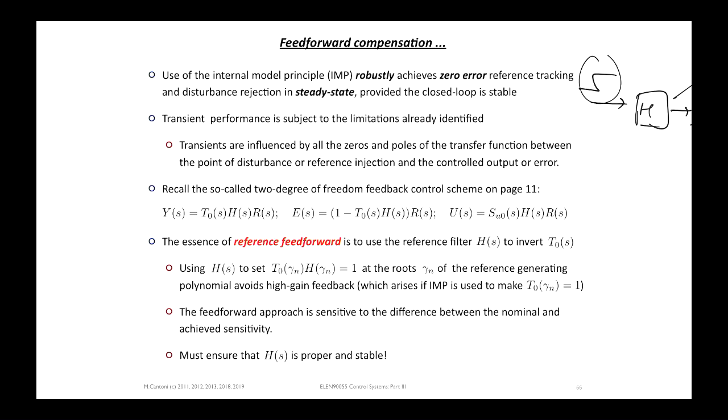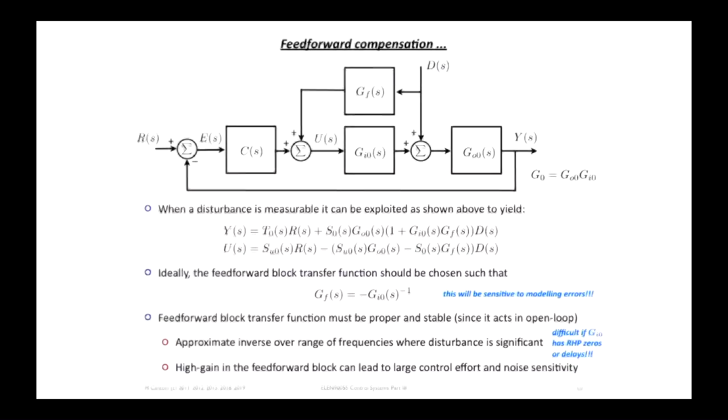So you'll know this with more certainty than you know the plant model, especially over low frequency ranges where we may have pumped the gain of the open loop transfer function up high, which will force T to be 1 over a wide range of frequencies up to the crossover frequency. So you do know T pretty well, at least over low frequencies, and so you can safely invert it, frequencies around there. All right, so that's the basic idea of feed forward.